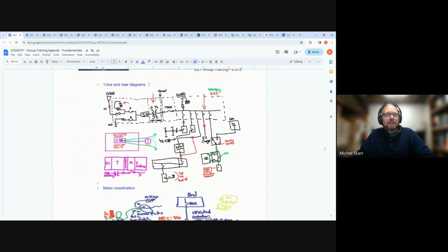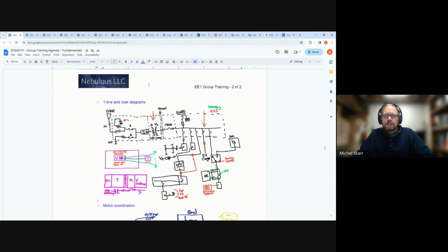service from the utility. Primary being one where the transformers are owned by the customer and also need to be maintained and serviced by the customer, whereas the secondary service would be at a voltage where the utility owns the transformer, maintains it, and replaces it if something happens to it.